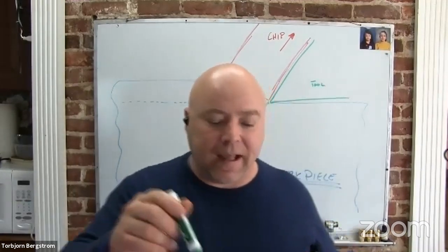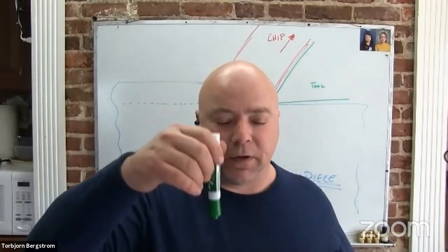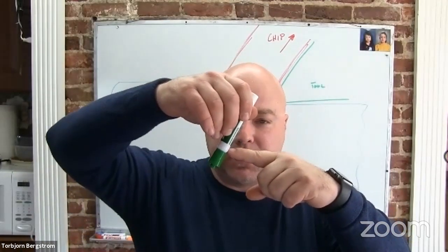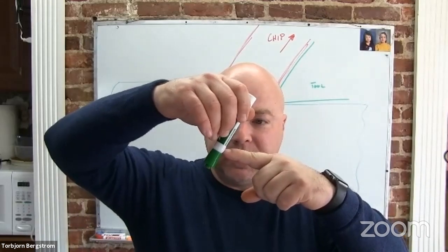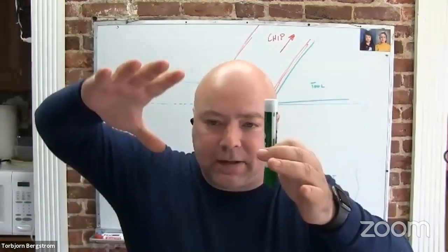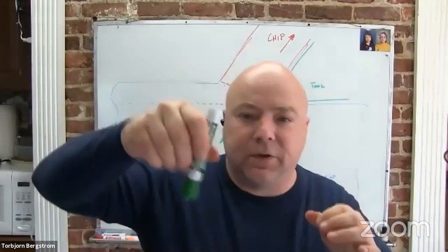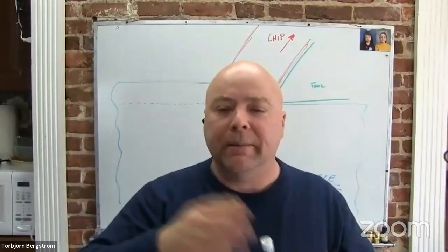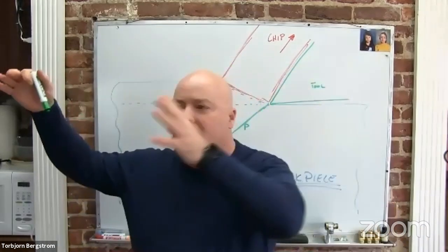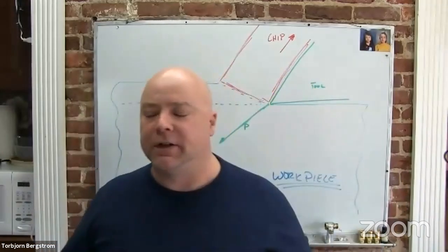And so that's a case where high forces can cause surface finish to change, because what happens is it causes the tool to deflect, and then eventually the tool can't deflect anymore because it's building up stress in the tool itself, and it pushes back, and the tool starts to spring back and forth, and it vibrates and it makes chatter. And so that's a case where increasing cutting force might cause the surface finish to be impacted.